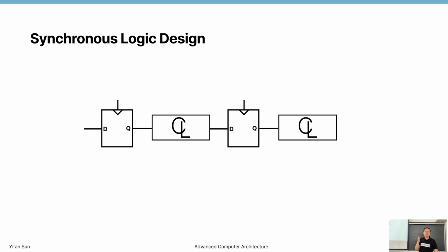If we can assume the combinational logic arrives at a stable state after some time, then we can guarantee Q. Let's say this is a rising edge, then D will spend some time to fluctuate, then it will become stable at the end.